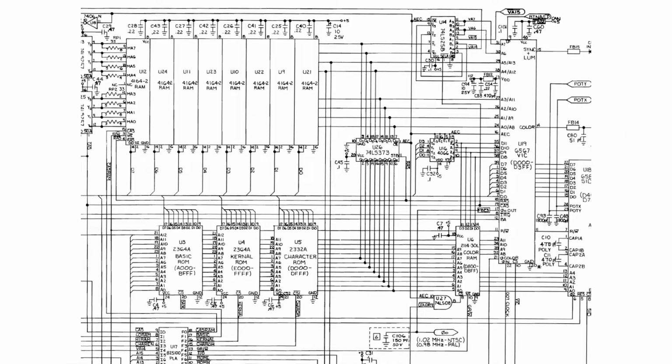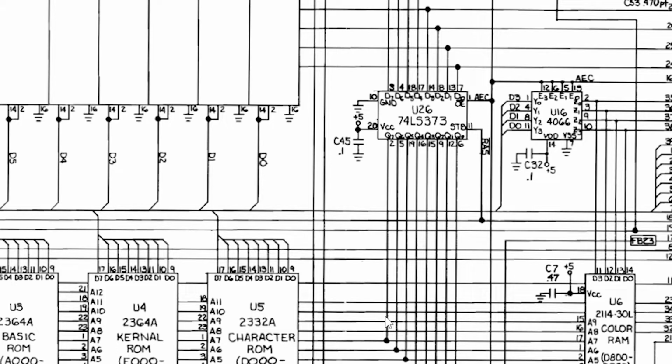So if I'm following address line 6 on the schematics, at least on this part of the address bus, I see it goes through a latch chip, which is the U26 or LS74373. We checked that chip last time, even though somehow I mixed up address lines and data lines, and it seemed to be fine, but we noticed that address line 6 was always low.